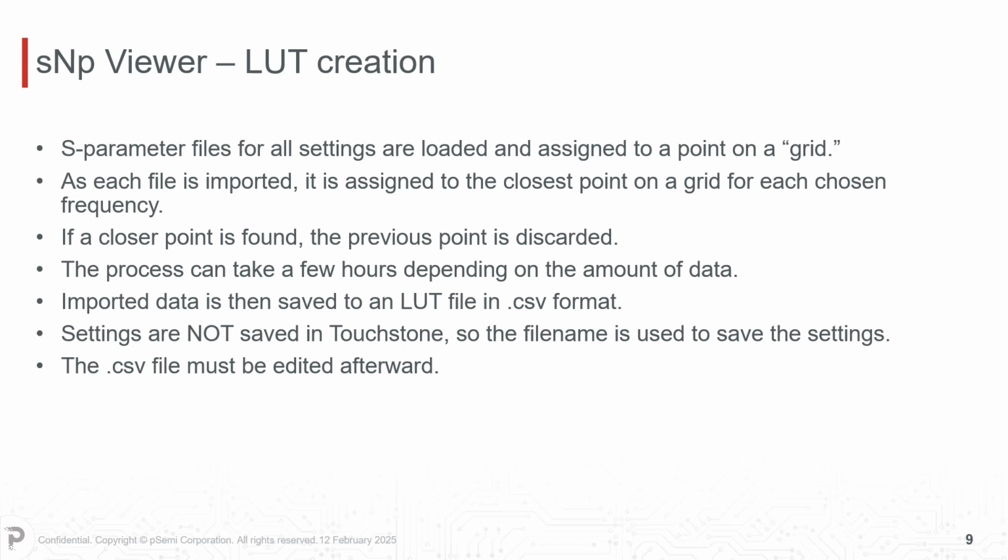Thing to note here is that settings cannot be saved in Touchstone files in a formal way. So the best way we have found is to use the file name to save the settings. The CSV file afterwards must be edited to separate out the settings.